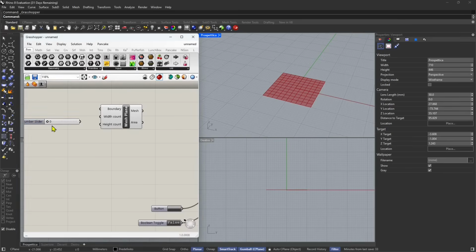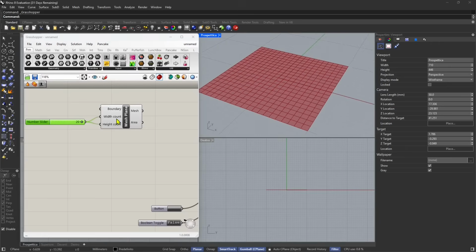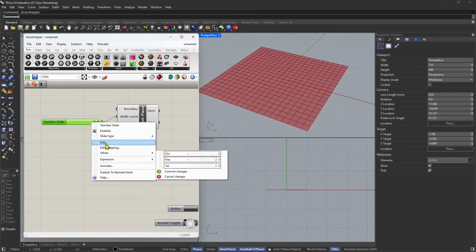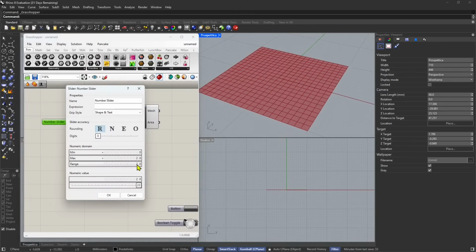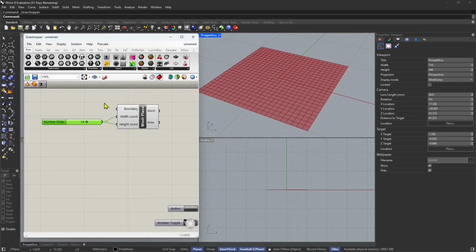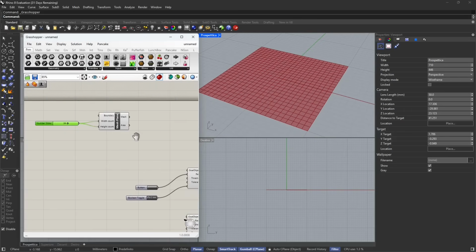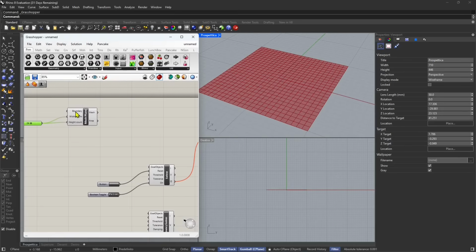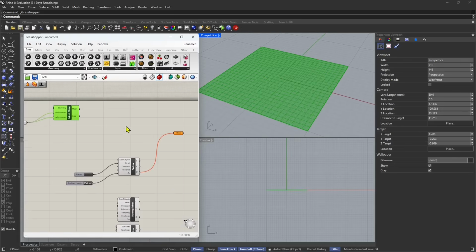Now, the more you increase the number of subdivisions, the number of faces, that is going to increase also the quality of the simulation, also the heaviness. So it's going to be heavier if you increase the number of subdivisions because it's going to take care of more faces essentially. Okay, so we can slide this. I input that in both width and height, so I maintain the proportions.